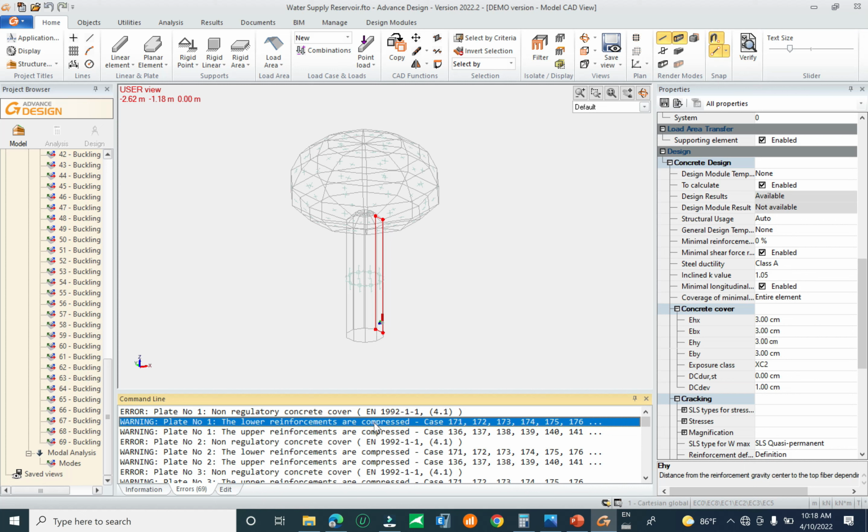First is singly reinforced, and the second is doubly reinforced. So a compression member is also required when the section cannot receive the tension reinforcement alone, and needs another compression reinforcement in this section to increase the bending capacity of the section. So to avoid this error, you can also increase the section of the shell.